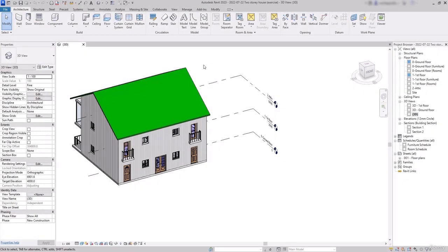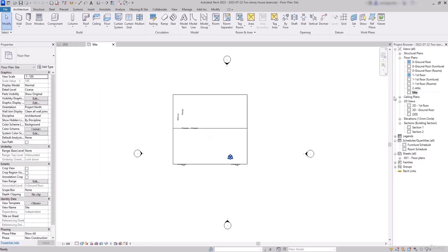So, have a look at this example. We are going to create the topography for the terrain where this house is located. Now, although I can create a toposurface in a 3D view, I recommend opening the site plan instead. As the view here is from the top, you will find out that it's way easier to place the points.